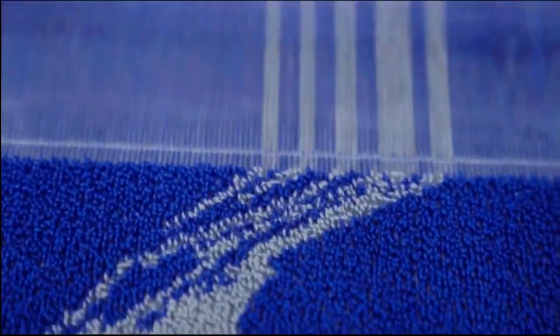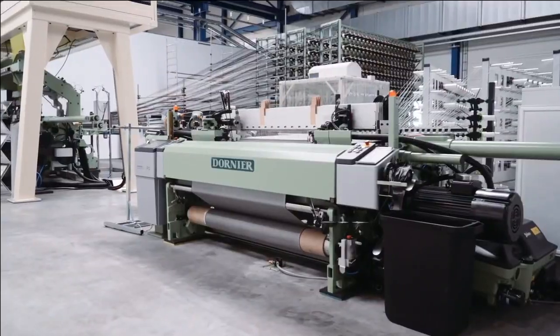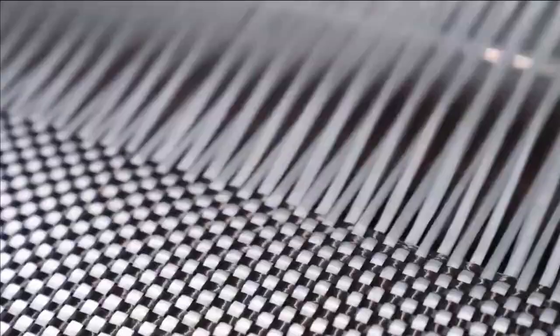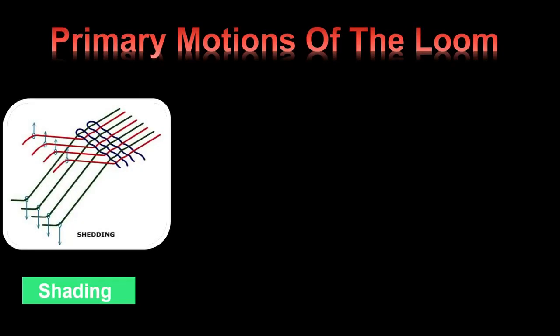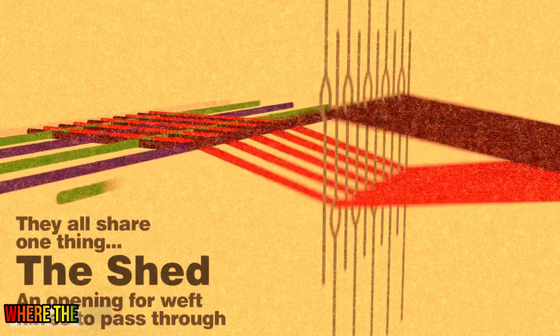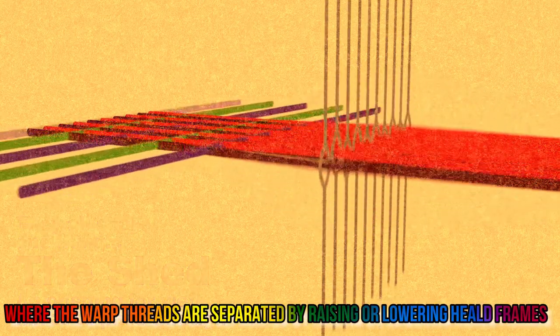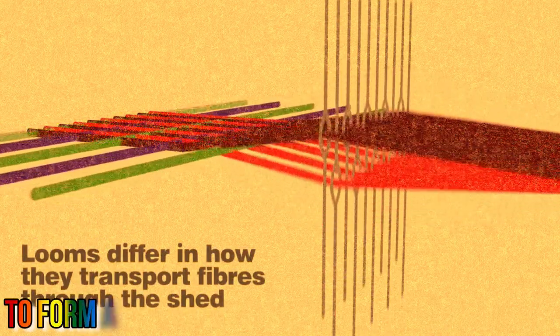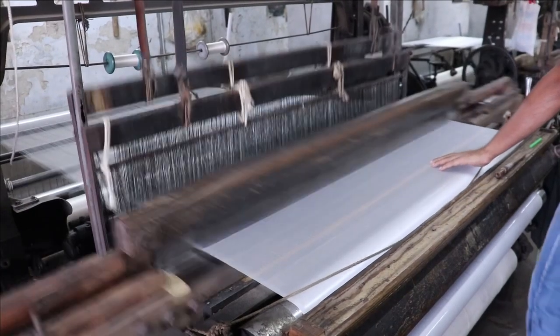Weaving. Finally, weaving is started, and other processes will follow for delivery. Weaving can be summarized as a repetition of these three actions, also called the primary motions of the loom: shedding, picking, beating up or battening. Shedding, where the warp threads are separated by raising or lowering heald frames to form a clear space where the pick can pass.